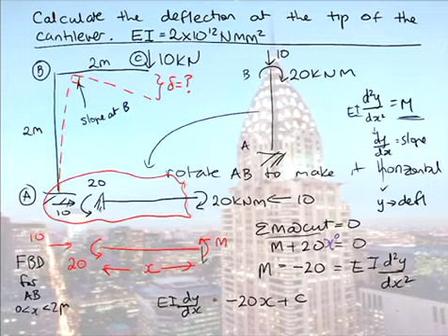Now over here in purple, I wrote an x to the power of 0. When you have a moment, in general, to be able to switch it on and off using singularity functions, remember, we multiply it by distance to the power of 0. But in this case, x to the power of 0 is always equal to 1. It's where you have, say, (x - 2) to the power of 0 that this expression either equals 0 or 1. That is because we enforce the singularity rule first, and the singularity rule says if the number is negative, it disappears. I know you all know any number to the power of 0 is equal to 1.